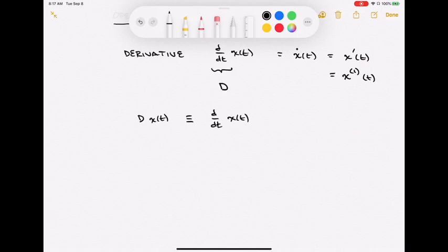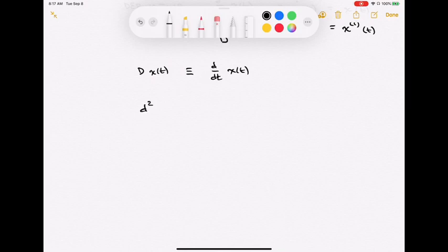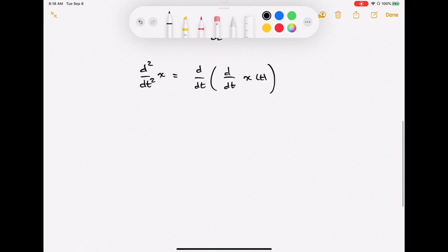And we're going to allow this notation to be such that we can do multiple operations, like taking repeated derivatives, just by repeatedly applying that D. And we're going to adopt a notation that looks a little bit like a polynomial expansion. So for example, if I did a d squared dt squared, in calculus, what does this mean? This means I'm going to take the derivative of some signal x of t. So if I was going to be complete here, I would have put an x on there, something that this is acting on. We said that we were going to use an operator notation, so we get a D here, and we're going to have another D and an x of t. And just because of its natural appearance of something that almost looks like multiplication, we can designate this as D squared x of t. So a D squared would just indicate a second order derivative, or a derivative followed by another derivative operation.